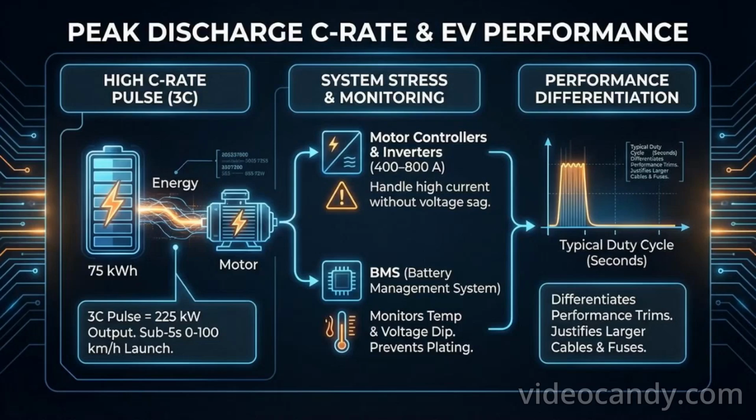Sustained high C-rate discharge is rare. Typical duty cycles last only seconds, but the capability differentiates performance trims and justifies larger cable and fuse budgets.